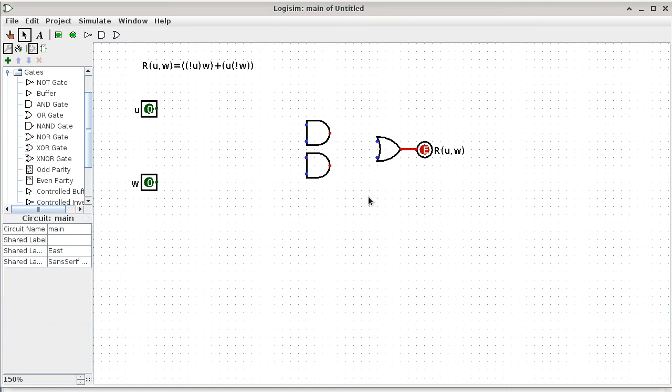Okay. So now we have 2 AND gates, and we know the AND gates feed directly to the OR gate, because you can see how the result of the AND and the result of the AND here are directly feeding into this final OR gate. So we just connect these lines. All right. So now we know we have to negate U to bring it here, and then bring W non-negated over here. We have to bring U non-negated over here, and then bring W negated over here.